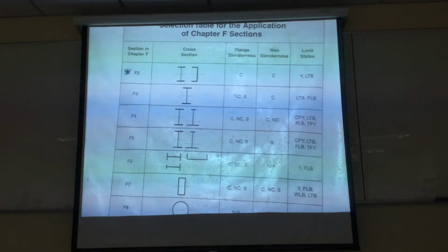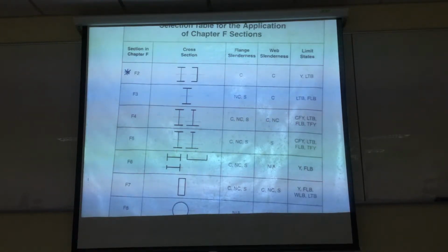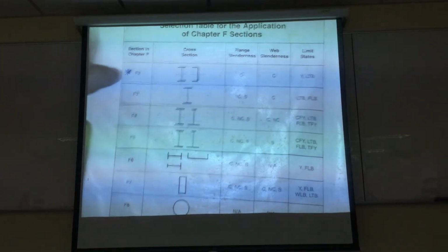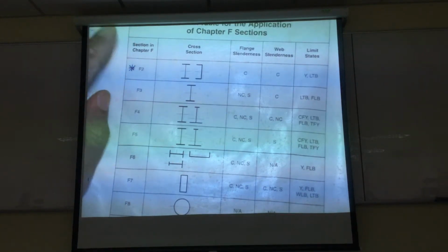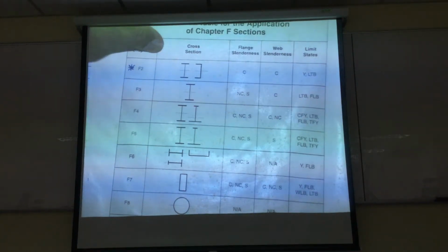So if you are in the design of steel structure, you need to make your steel table, and then you can check the compact and non-compactness for each section that you have, such that you know if the formulas and recommendations are applicable to the case that you are dealing with. But this case will be the general one that you are going to use.